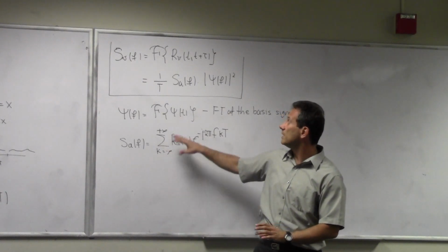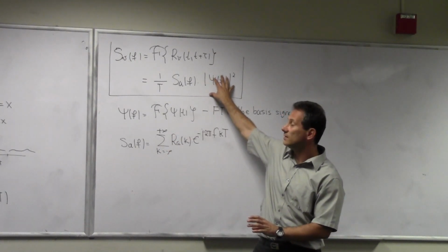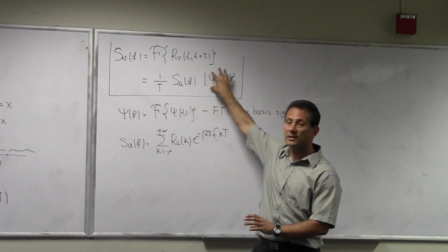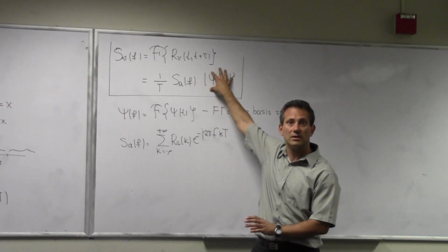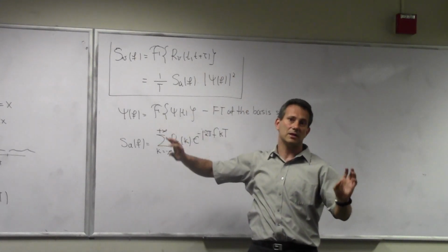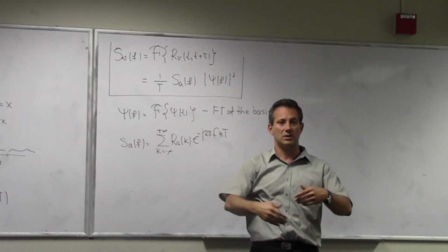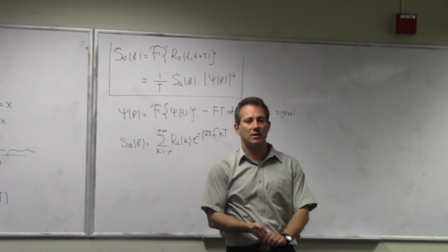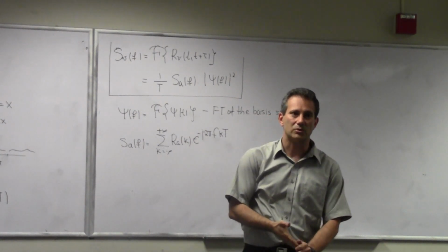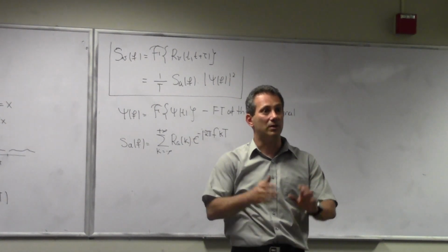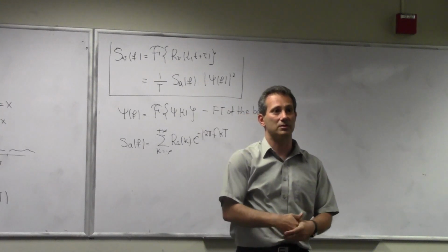If you go through this math, your signal in the frequency domain looks like the pulse that you have selected for the signal. So now that we know that, next time we need to actually put some constraints on this pulse, and you will see there will be a whole range of pulses that will allow us to signal over a band-limited channel without intersymbol interference.